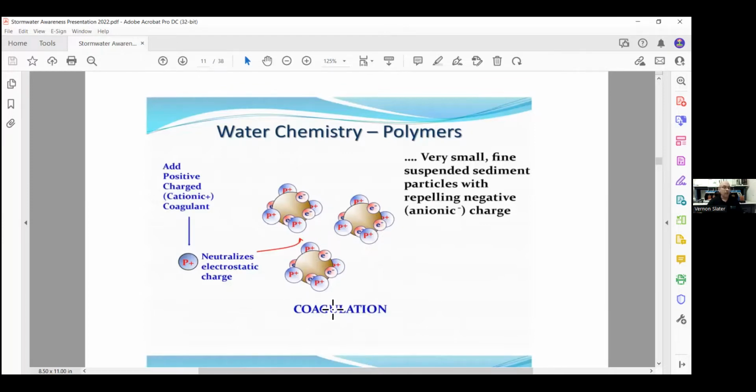After the settling period, the cleaner settled water is sent to filtration. Turbidity is removed because the chemicals bind with anionic suspended solids, causing them to combine into larger masses and settle out. After the settling period, the cleaner settled water is sent to filtration, where the long chain polymers with the attached particles can easily be filtered out. After some operational time, the trapped particulate will begin to clog the sand filter and backwashing will become necessary. This process reverses flow through the filter and out separate plumbing back into the headworks or into a designated backwash tank.